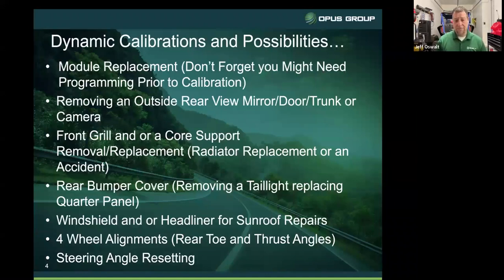Steering angle sensor resets. ADAS works off of steering angle. A lot of it works off of, hey, you did the alignment. Certain manufacturers, once the alignment's done, you've got to reset the steering angle sensor. Start digging through the SI, because you guys could very well possibly need to calibrate something on the car that goes along with that as well.